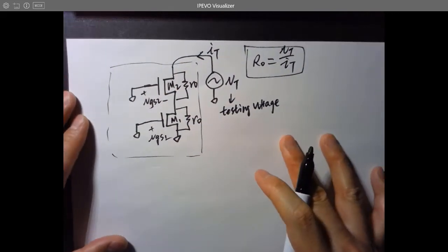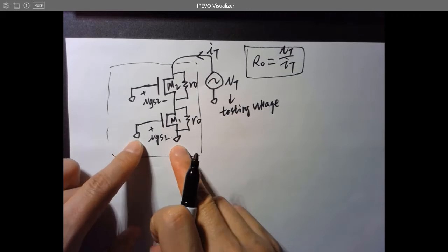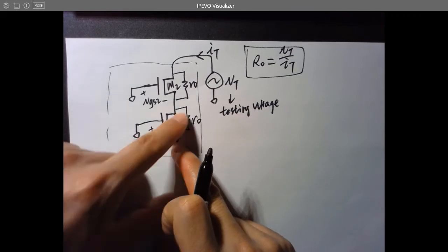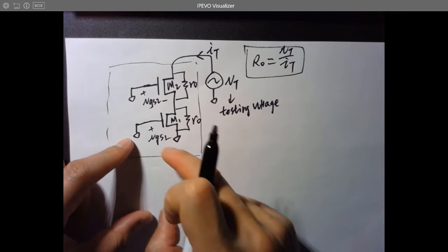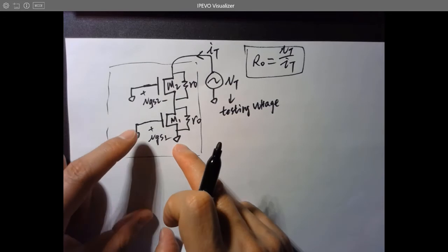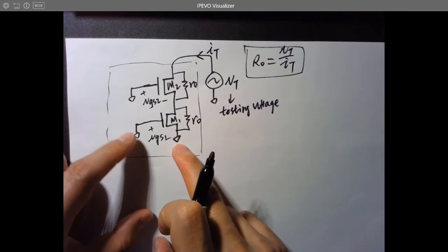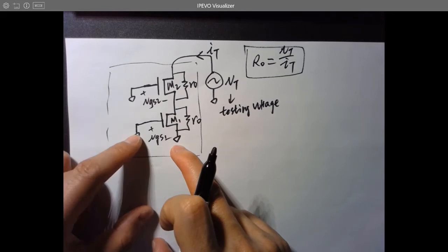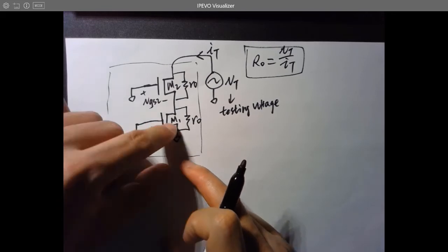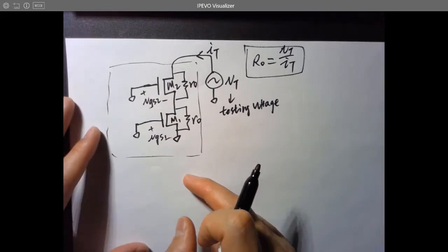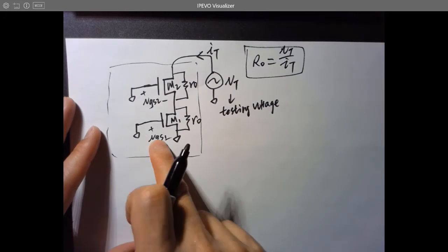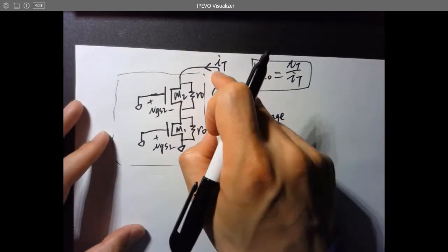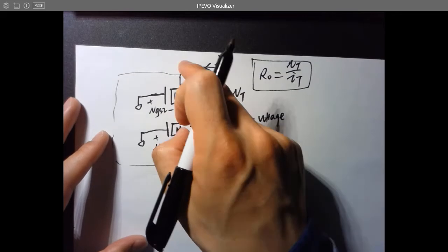And now I can find out, actually, this is ground to ground, even though it's talking about the AC analysis for this NMOS, but the thing is they have two DC ground being connected to the two terminals of VGS1. So there's actually no AC current that can flow through this being generated by VGS1. Okay, but there's still an AC current over here, which is IT only.